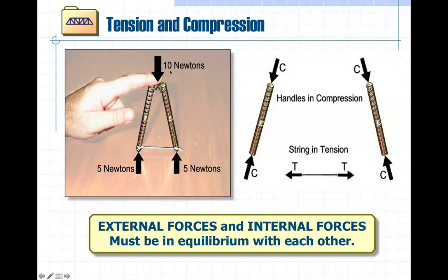Now these big arrows I have here, these are external forces, right? I'm pushing on it from the outside of this structure, and the reactions are external as well. The internal forces are the things I use to figure out how big the handle needs to be in order to keep from breaking.